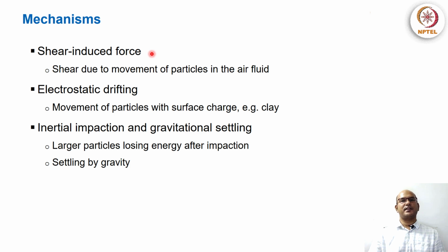The next thing is shear-induced force: when the particles are moving in the fluid, there is a shear force exerted, and this will also influence the overall movement of particles. Then we have electrostatic drifting. If the particles themselves have some surface charge, for example clay, they will move towards the opposite charge surface just by electrostatic drift.